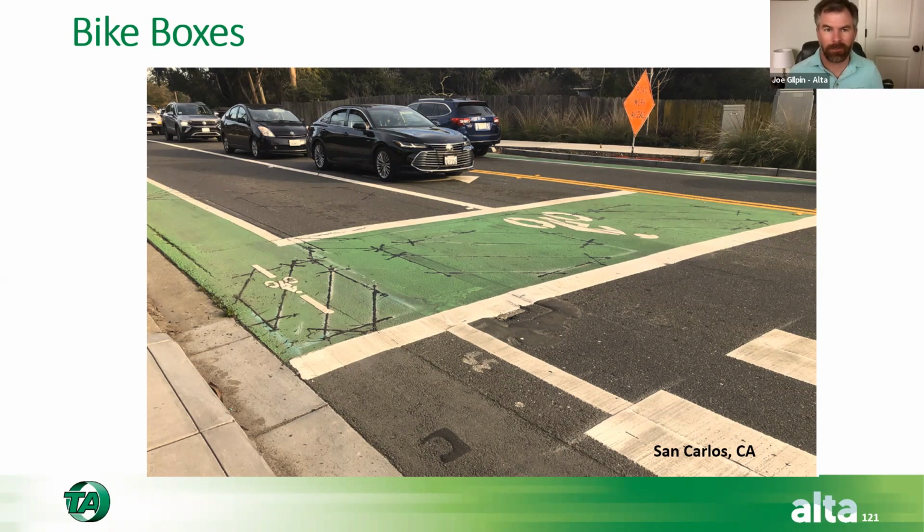And so there is a requirement in the interim approval where you have to have a pedestrian countdown timer at the intersection so that when you make that 90-degree turn and you're now broadside to traffic that could be released, you at least know how many seconds you have left to finish your maneuver, which virtually every signal should have by this point. But it is something to think about. Another reason why I don't prefer to use a bike box to turn people in left directions.